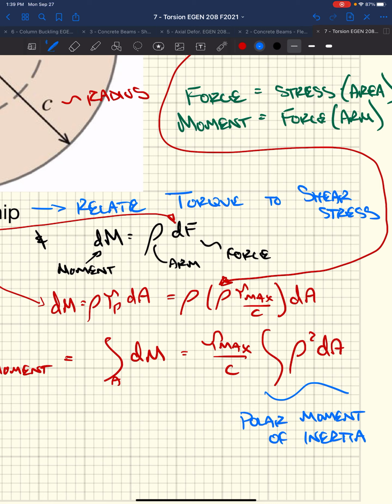All the polar moment of inertia is, is your regular moment of inertia, like we had I sub x, I sub y. In columns, we were looking at all of those moments of inertia. Well, the polar moment of inertia is just the resistance to twisting of a cross section. So you now have this axis running along the longitudinal direction. Well, this is calculating how stiff your shaft is with respect to rotation.